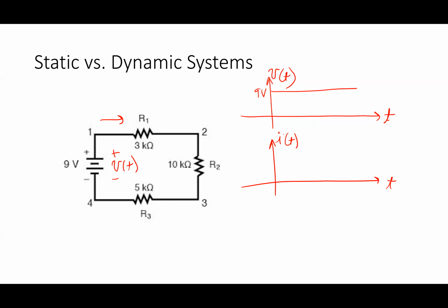Not quite a constant, you're almost right. Well, it wouldn't slope upward, right? It would be flat, right? It would be a constant, but it would be a constant starting at time t equal to 0. When I turn the power on, that's when this guy starts going. Okay, the current's a flat thing. So in this case, I got 9 volts and 18K. So I think that's, well, I'll just call it 9 volts divided by 18K.